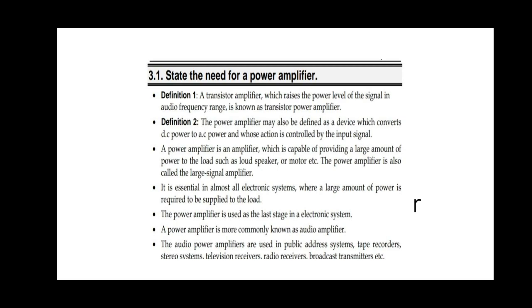Output impedance is divided by 1 plus A beta: ZF equals Z by 1 plus A beta, where Z is the open loop output impedance, ZF is the closed loop output impedance or negative feedback impedance. Beta is the feedback factor, A is the open loop gain.